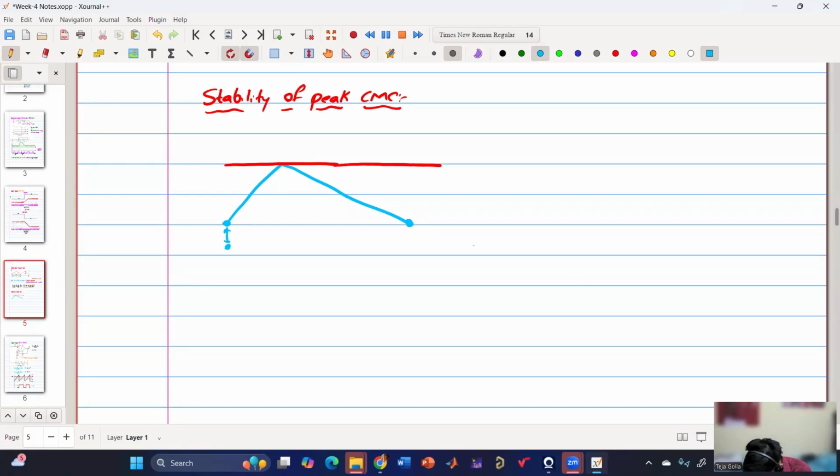So this is the perturbation and it goes here and then it comes here. Now we have to see how this is getting changed. For any perturbation in this IL tilde, how is my waveform changing? If the duty ratio is getting perturbed, we need to check whether that is trying to improve or degrade. So now this is say IL1.